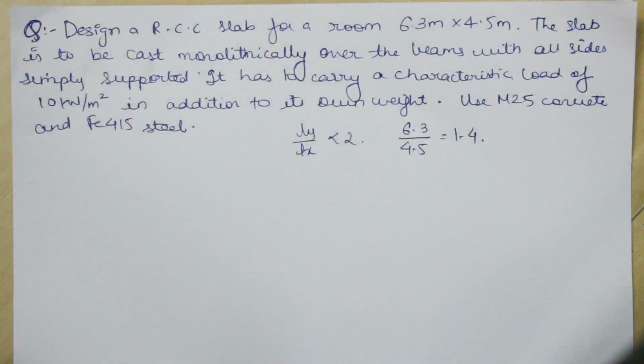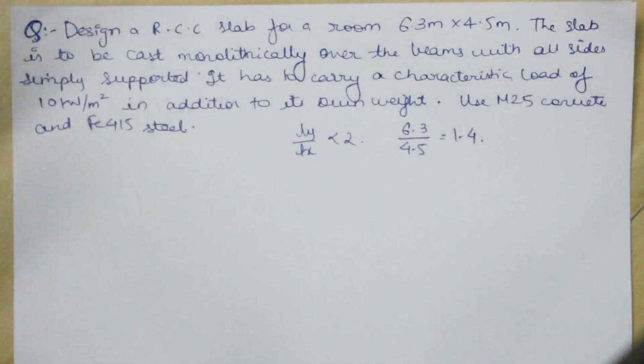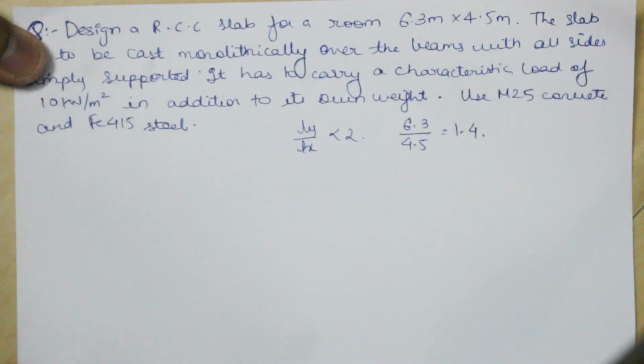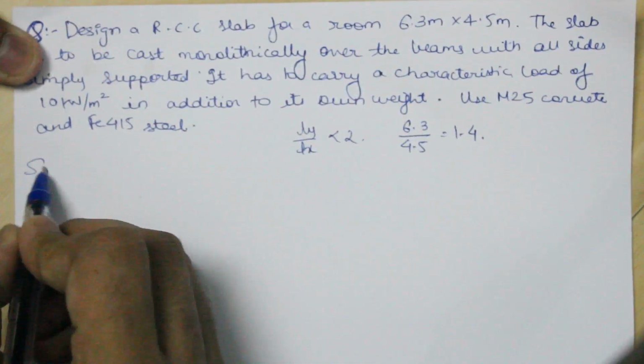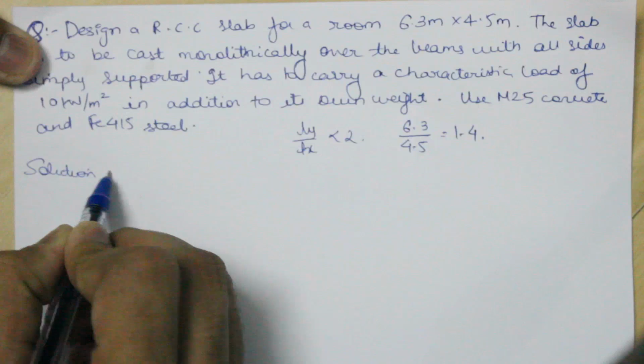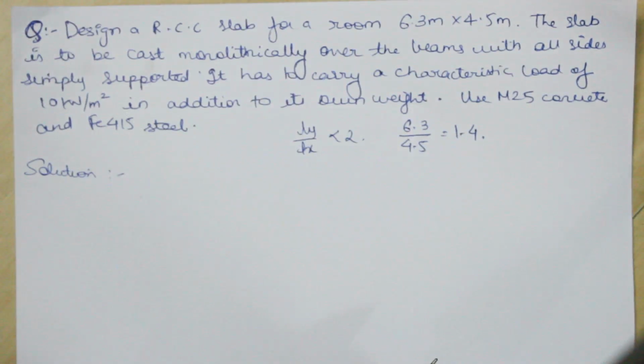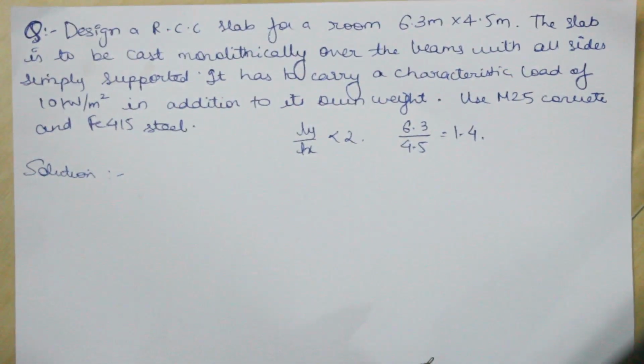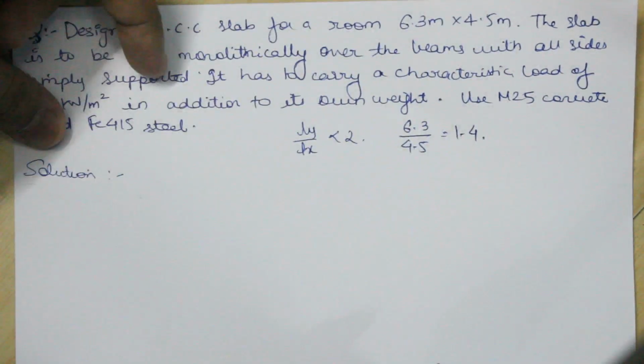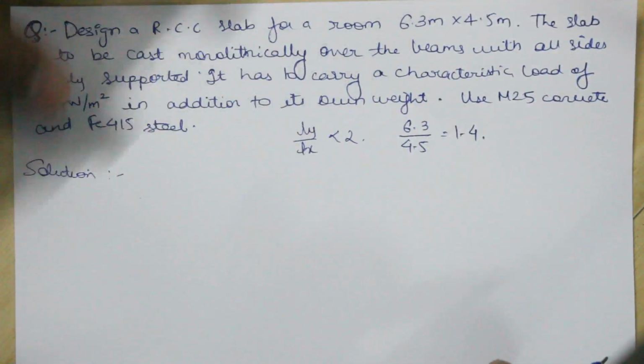So before we start, the first step would always be to calculate the effective depth of the slab, and the depth of the slab can be calculated by using the span by depth ratio. So it is given in clause number 23.2.1, it's on page number 37.